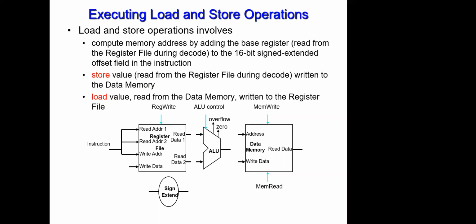Just to remind you of the load word as an example. The load word will define a couple of things. First, it will define from where I should grab my data, correct? From where will be defined by two things: what is my base address and what is the offset, correct? So I know in advance right now that I need my ALU to do either an addition or subtraction to calculate exactly the address, because with that offset, I might add or I might subtract. Correct? So I know now in advance that I have to have the ALU in order to execute my load word. And the same applies for the store word, correct?